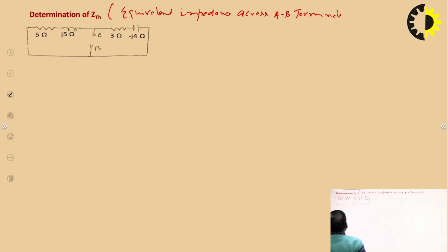So this is the circuit diagram. We have removed the ZL and replaced voltage sources by their internal impedance. The voltage sources are ideal in nature, so they have 0 resistance as internal resistance, and 0 resistance is replaced by a 0 resistance wire, so it looks like a short circuit.